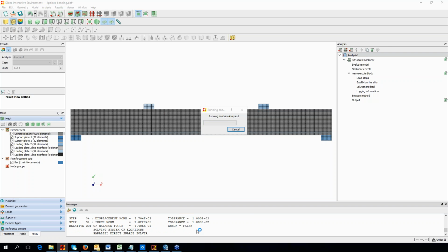So it means that you can replay this Python script at any stage, which might be very convenient if you want to rebuild your model, just changing some parameter. And Python also offers the possibility of loops and programming, so it's quite a powerful tool. I will show you in a moment where to find the Python script from your model and how to run it.